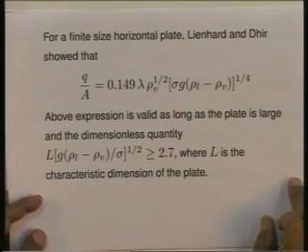I am not giving them here, but there are expressions available for other geometries like horizontal tubes, etc., for the peak heat flux. Now, finally, we come to the film boiling region. First, we have the transition boiling, and you recall my describing to you that transition boiling is the region in which the Q by A value decreases as T_w minus T_s increases.